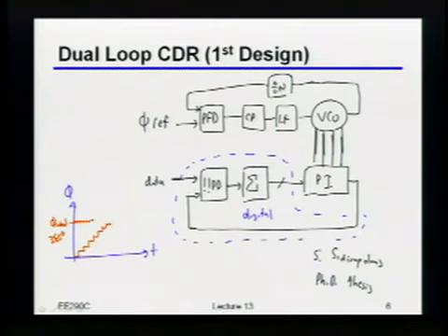Oscillate. Okay. So now what Shiva said is it's going to oscillate. So the other thing that's actually kind of subtle but very clever about this is it turns out it depends a lot on how you've actually built that DLL. If I had an analog DLL where I was just analog adjusting a delay, then if I didn't have more than 360 degrees of phase range, then I would just get stuck, right? I just couldn't do anything anymore.